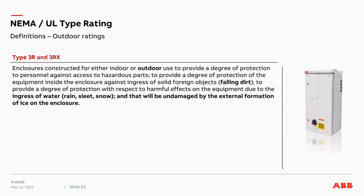A Type 3R and 3X enclosure is designed for indoor or outdoor use. It gives you a degree of protection against personnel and falling dirt. It also protects you against the ingress of water, rain, sleet, or snow, and will be undamaged by external formation of ice on the enclosure. This does not mean you can wash it down with a garden hose. It's just for rain, sleet, or snow.